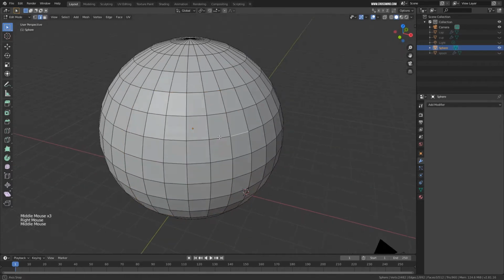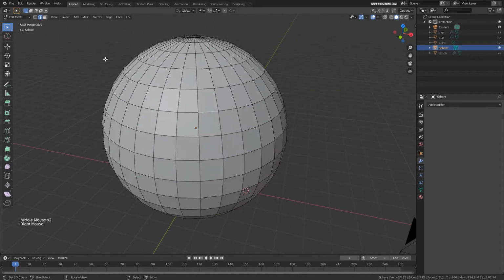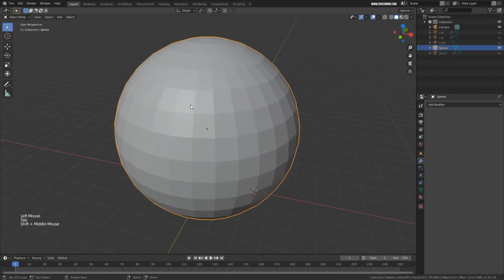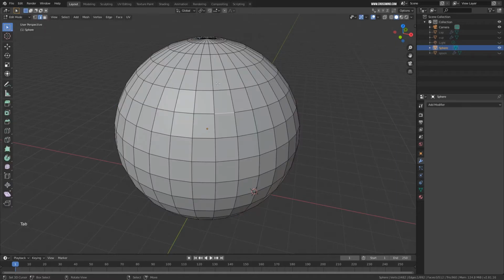Now if you want to study it more, you can go to the Select menu over here. Just notice when we are in object mode, these menus are very limited, like View, Select, Add an object. When you press Tab, then these menus will expand, and there will be many other options available related to mesh editing.